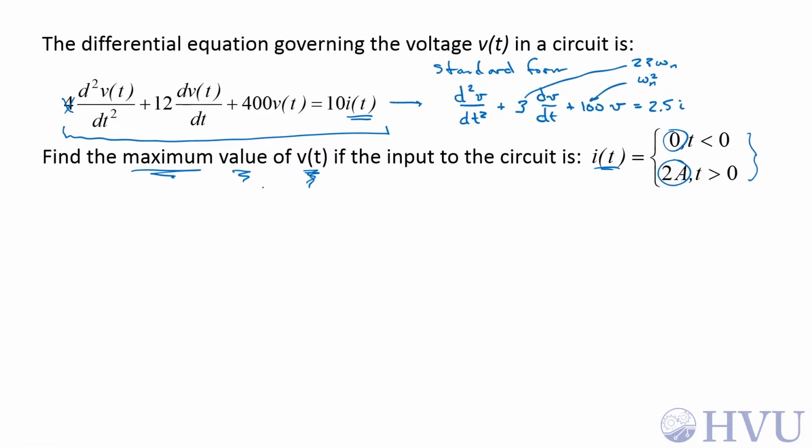So the peak value, by definition, y sub p, is the steady state value, so y_ss is equal to y as t goes to infinity, times 1 plus M sub p, which is the percent overshoot. Also, M_p for underdamped systems is approximately 1 minus zeta over 0.6 for zeta less than 0.6.